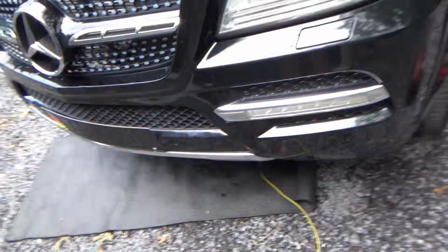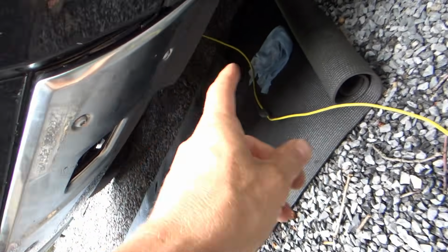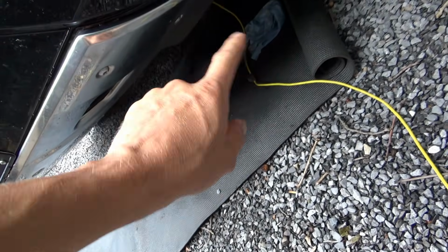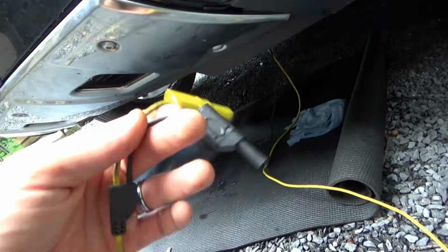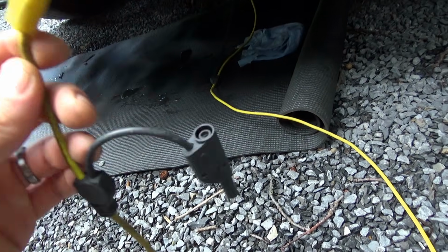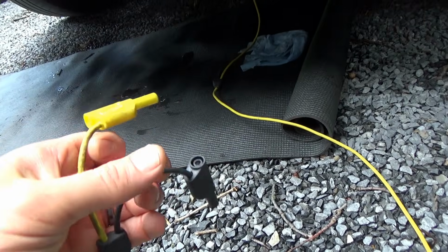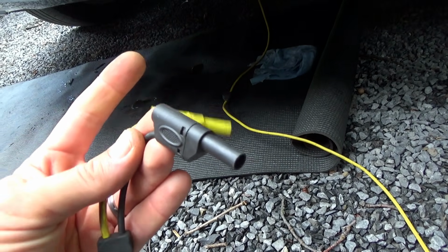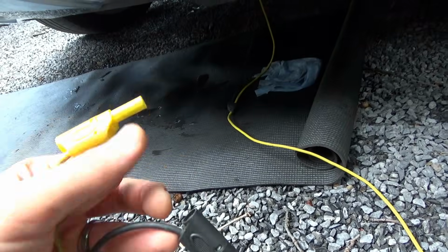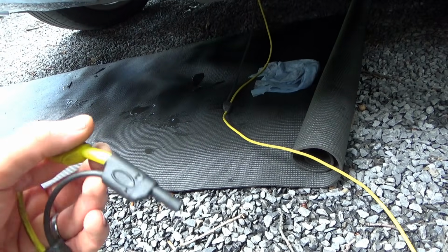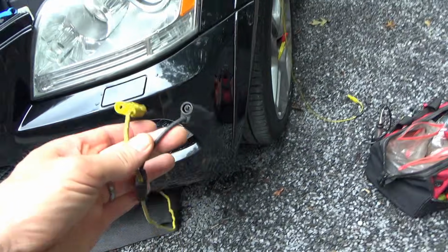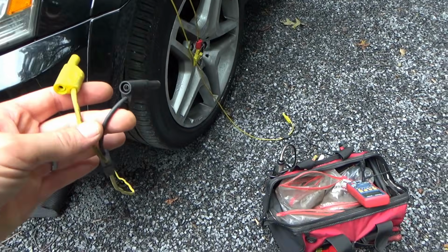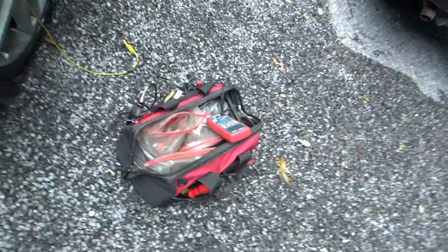Alright, so to make things a little easier, I crawled under there, disconnected the compressor on that feed wire, and attached two leads with piercing probes. So the yellow lead comes from the HVAC controller, and the black lead goes to the AC compressor. Okay, so basically if we connect these two, it'll be like a connected circuit like the car is supposed to have. So we can do all of our experiments with these two leads. What do we want to check first?